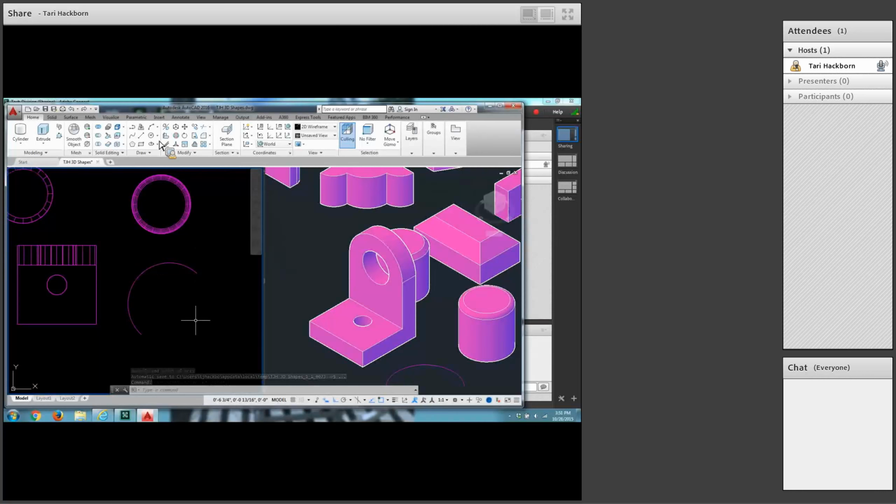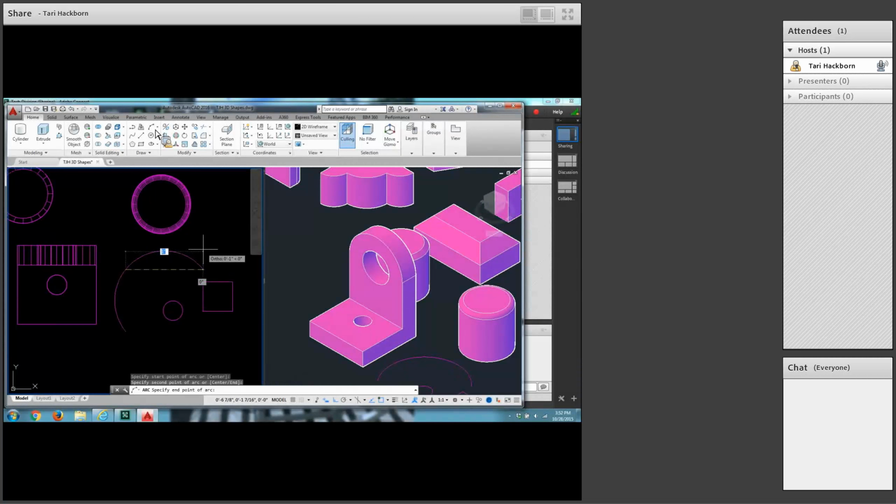Draw a circle with an 1/8-inch radius. Okay, circle with an 1/8-inch radius. And then draw a rectangle, and each side has to be 3/8. So do at 3/8, comma 3/8. Okay, after you pick the starting point. I don't really like my arc, so I'm going to erase it. Let's try that arc again. Oh, I know what's happening. Ortho's on, and it's always making me pick a spot that's right above it. See, I want it to be kind of shallow like this. Okay. All right.